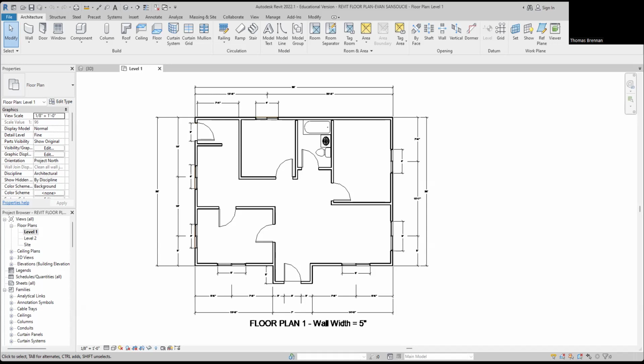So you've got this going on. Each one of these operates in a different way. To decode something like this, you first have to take a look and see what my sheet tells me. When I look at the sheet and see what the scale is, it says scale as noted. What that means is there is not necessarily one master scale here because there are so many different views. Since there are different views, there could be different scales for each one. So you have to pay attention to that.